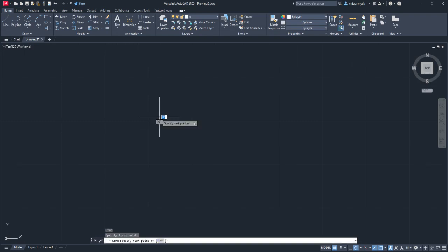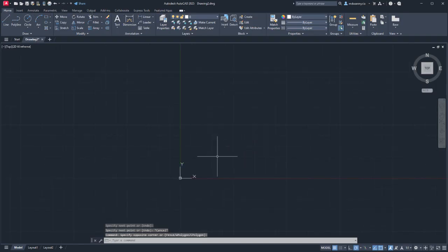So, for example, when I'm drawing out here, see how it's going up only in 1/16 of an inch, so 7/16, half inch, or 8/16. So it's only recognizing those fixed values, but I can go in between the values. So I can start and I can go just shy of that, and it's still going to draw it to that point. It's just that the number it's going to round it to visually for our use is sort of irrelevant to how it's going to put that number down when it's showing it. So just keep in mind that there is a place to change those settings, but I wouldn't mess with them too much.